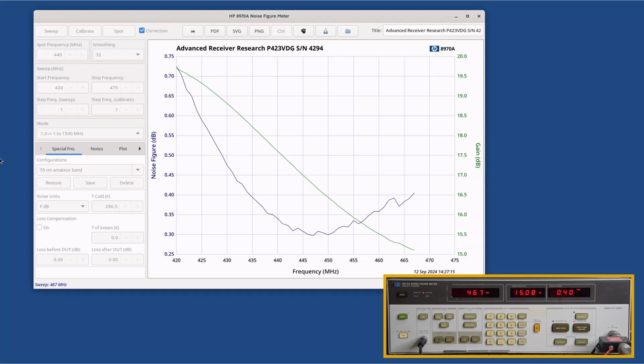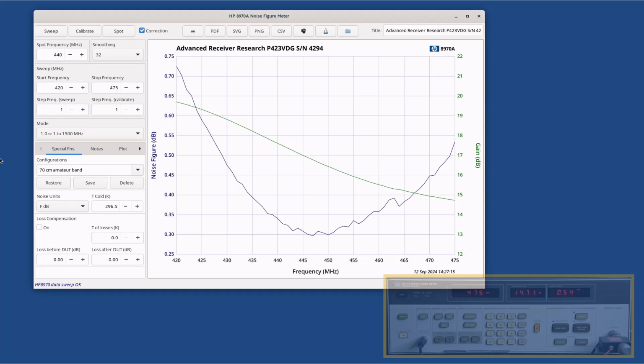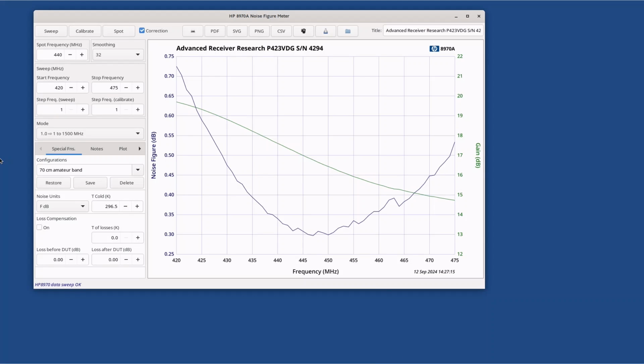If set to auto scale, the plot will rescale when necessary based on newly acquired data. If a static fixed scale is preferred, disable auto scale and set the coordinate scale bound on the notebook plot page. If the memory trace is shown, the auto scale settings use data from both the memory and the measurement traces in setting scale boundaries.